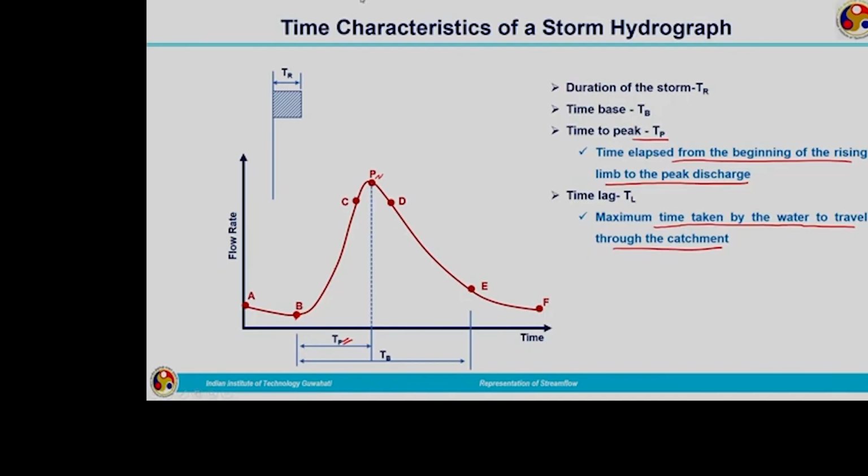Then what will we be doing? We will be finding out the peak of runoff, when it is occurring, that time minus the centroidal time of the hydrograph. So, how we will determine this time is by considering the centroid of the hydrograph and the point where all the catchment contributes water at the outlet, that is the point of inflection D. All the storage components will be satisfied at that time. It represents the maximum storage, that is the point of inflection.